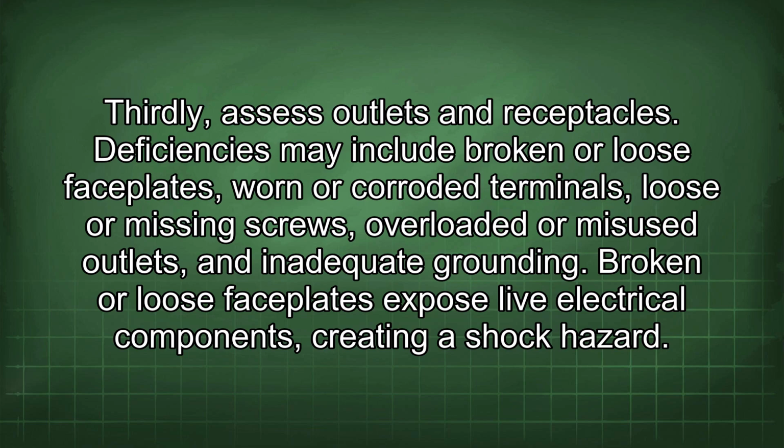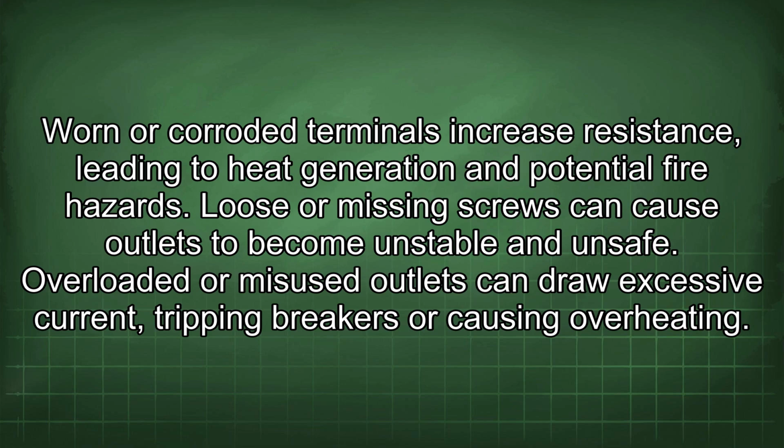Deficiencies may include broken or loose faceplates, worn or corroded terminals, loose or missing screws, overloaded or misused outlets, and inadequate grounding. Broken or loose faceplates expose live electrical components, creating a shock hazard. Worn or corroded terminals increase resistance, leading to heat generation and potential fire hazards.